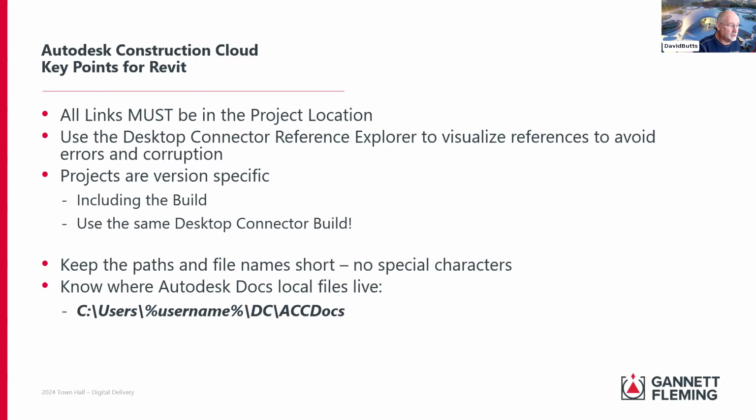So there's two things in here that we want to talk about. If you have a CAD file that's linked to somebody's local hard drive and somebody opens up a Revit model, you're going to see a warning. And some of you might have already seen this. It says the requested service is not available. If you're a Revit user and you're working in the cloud, I guarantee you've probably seen it more than once. That's typically referring to the fact that a file cannot be found. It's somewhere linked in a linked file. It's a nested link somewhere else, and it's in a location that somebody in the cloud doesn't have access to.